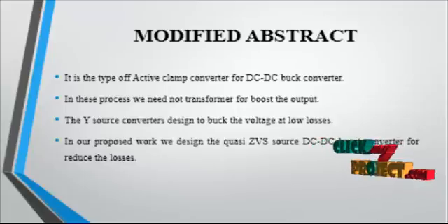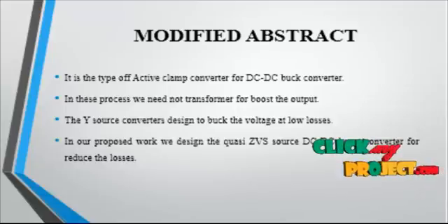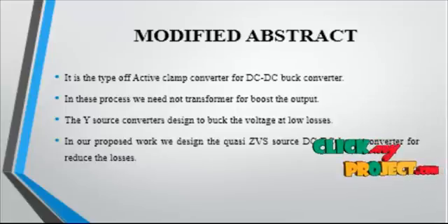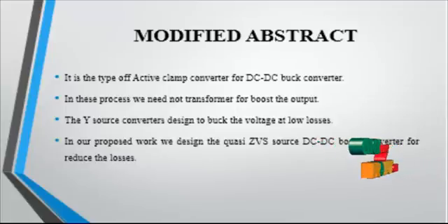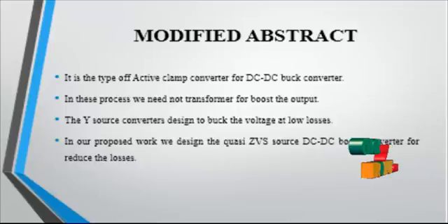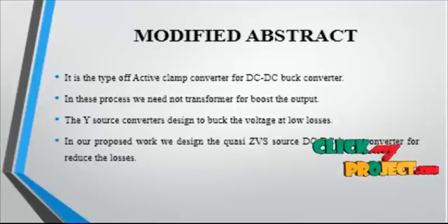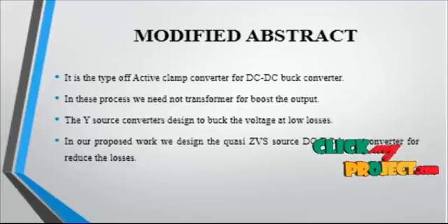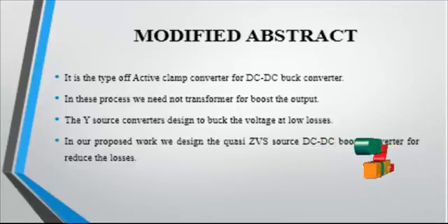An analysis that takes into account the presence of resonant elements is presented to establish the condition of stability. This method correctly predicts the stability of current controlled active clamp converters. A simple expression for the maximum duty cycle for subharmonics free operation is obtained.